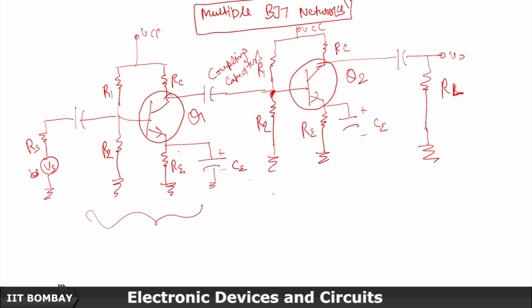So you can say this way, you can try to amplify the gain if you are using such multiple stages. So the capacitor here basically makes sure that the DC bias of this and this are independent, and only connects the AC signal basically. Also these bypass capacitors are here, they make sure that the AC signal passes through from here, short circuit, and doesn't change the bias point basically. Similarly here. I'm just considering the case of two stages here, but I can have a case of multiple, like n number of such stages.